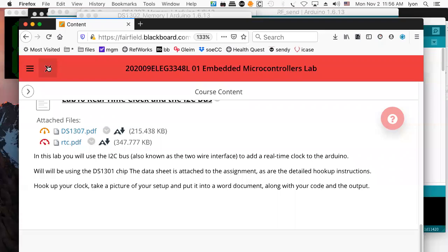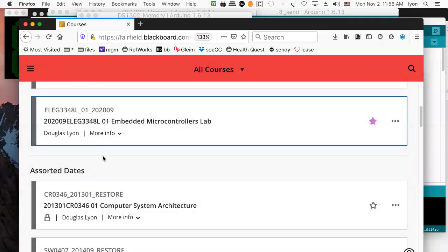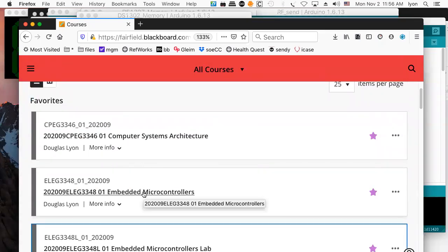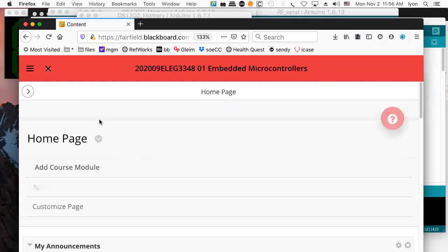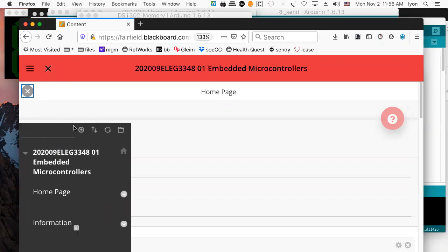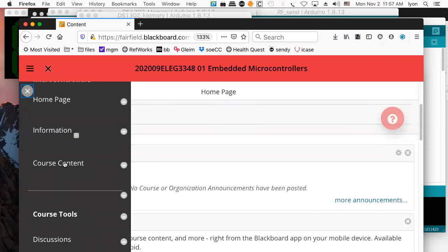One of the things that we've been sort of skirting around on the details for is serial ports. And I really did want to get into it because the I2C interface is really a serial interface. And as a result, we're going to need to know how to do serial communications for a couple of reasons. First, I2C is serial, and so we're doing a serial interface. Second, if we want to type into the Arduino and have it read our instructions and then type back to us, that's using a serial interface.